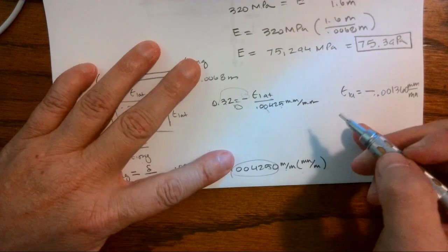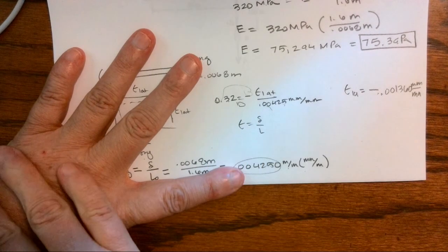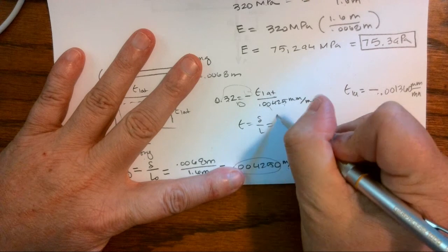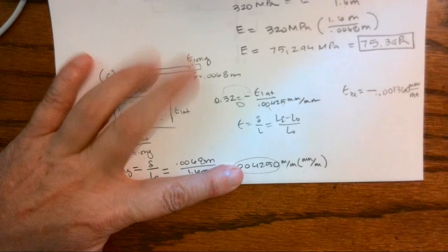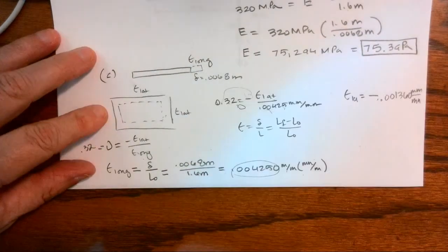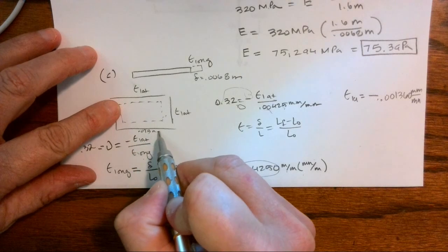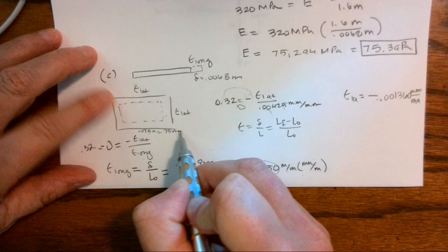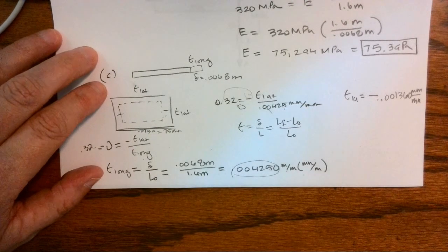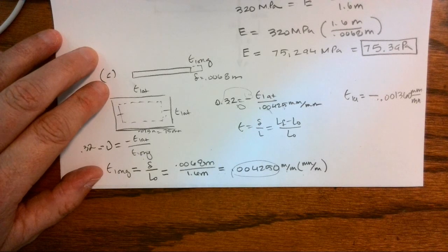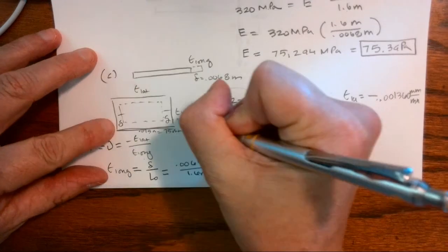So what is strain? Strain is change in length over length, which is length final minus length initial over length initial. So if I want to know what is happening to my dimensions, and if I start out at 0.075 meters or 75 millimeters, okay, I'm getting smaller. And the question says, what is the change in lateral dimensions? So I don't really care what the final length is. I just need to know what is this change in my dimensions.